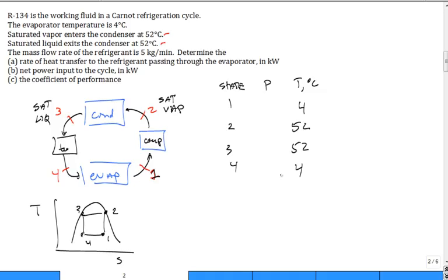Now, what about our pressures? You just have to go get the table and look up those P sats at that temperature. Okay. Let me do this in the interest of time. I have it worked out on the next slide. I'm just going to outline again how to calculate it, then I'll jump to the next slide and show the numbers. Okay? But everybody should be able to do that, right? Once you have the pressures all figured out, there's really only 2 pressures, the high pressure and the low pressure, and that's it. Then we can talk about the quality.